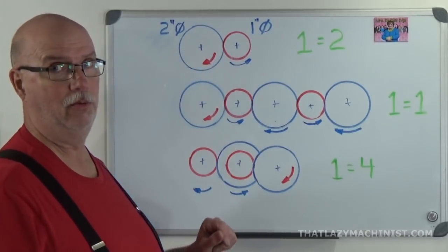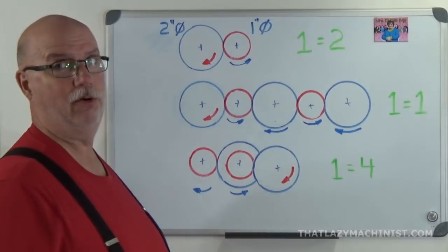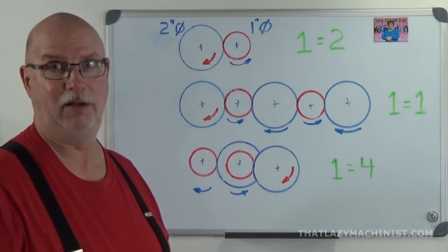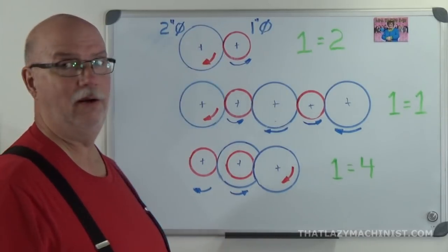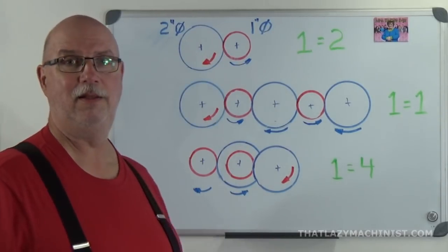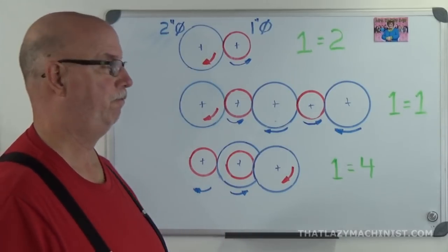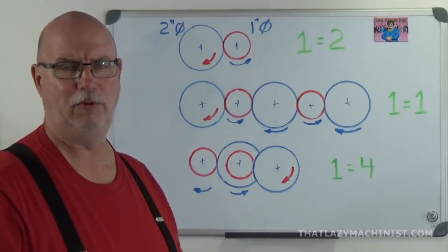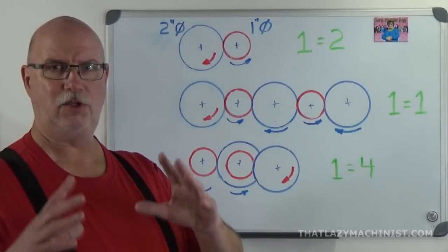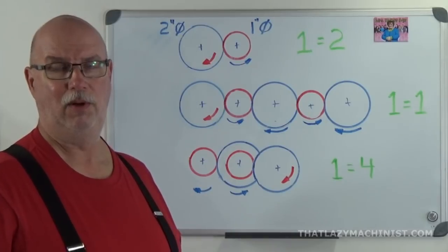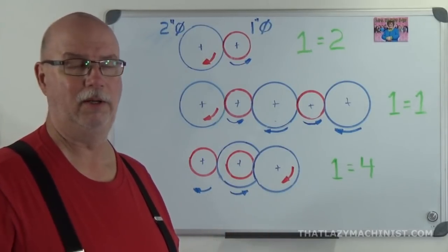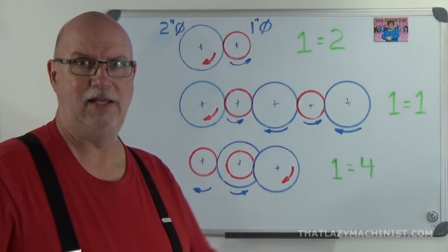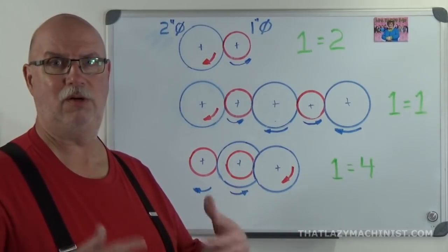One gear, the blue one, because of the red arrow that I've drawn on it, is the driver gear, the one that is driven by the motor. And the red one here with the arrow underneath is the driven gear. Now, if we look at this and we remember, everything in gears is proportional. So if one gear is twice the size of the other, well, the relation is going to be 2 to 1. If one gear has twice the amount of teeth as the other, we're going to have the same relation, and so on and so forth.